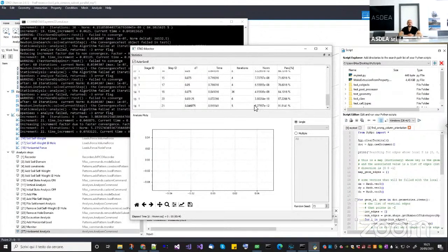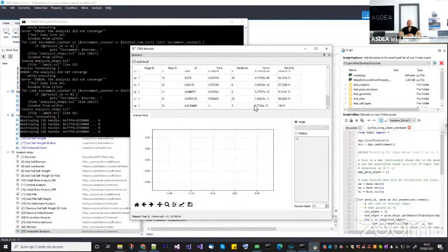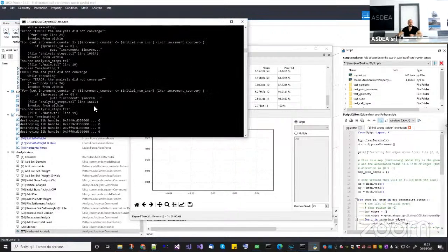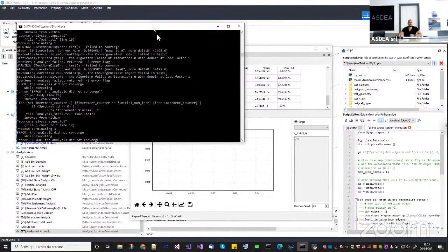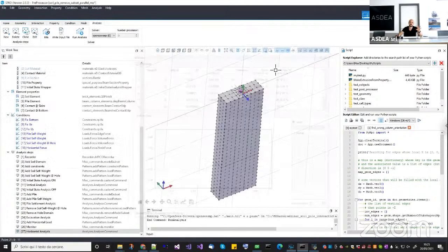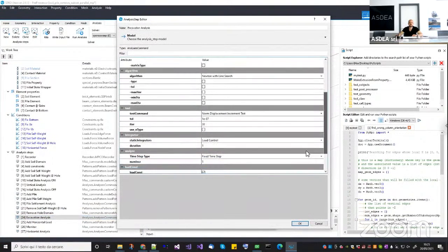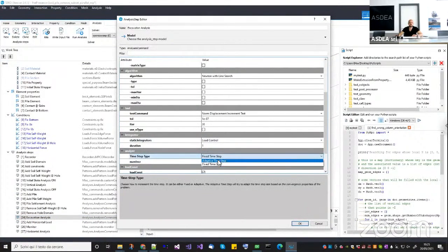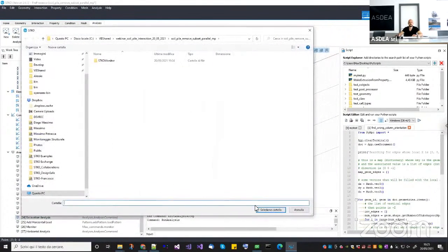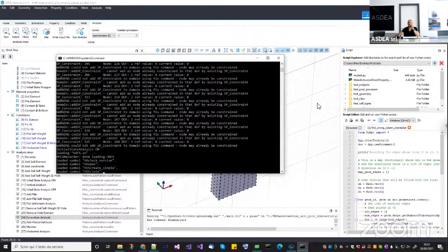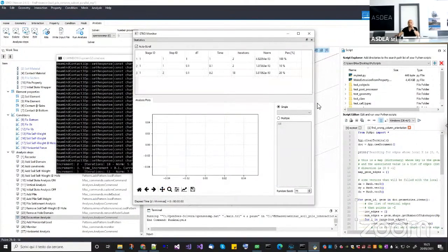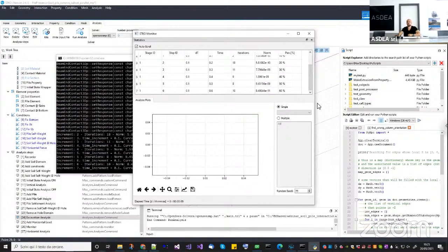Now, I'm afraid that the next step, when you perform the whole, one step will not be enough. And in fact, it is not enough. Okay, so you can try removing the whole now. Before it was a linear analysis, now you have a contact, so probably the excavation analysis should be something like an adaptive time step with at least 10 steps. Let's see. In the meantime, I need to answer to Begum. This answer will take a while, so just let me wait a couple of minutes for this.